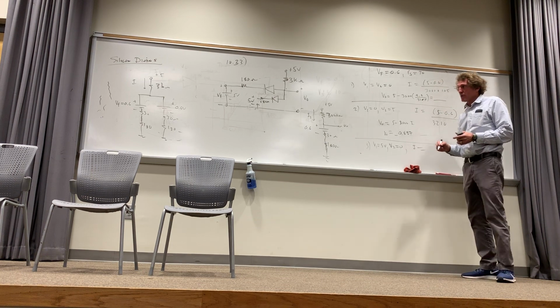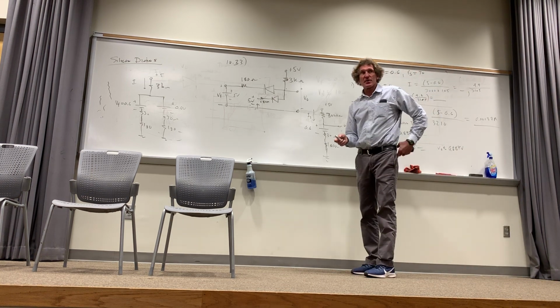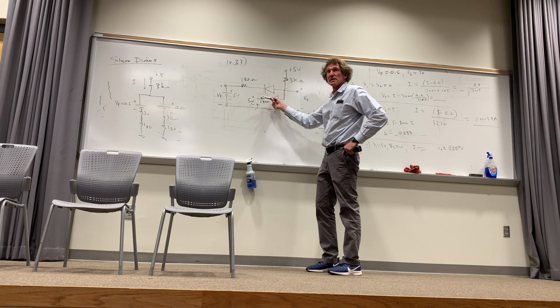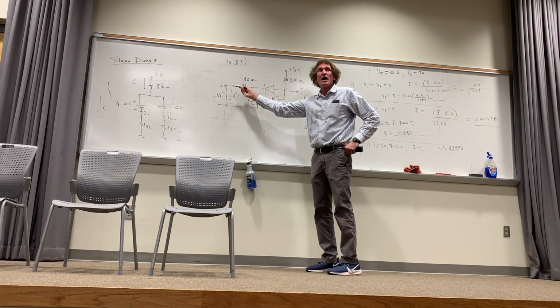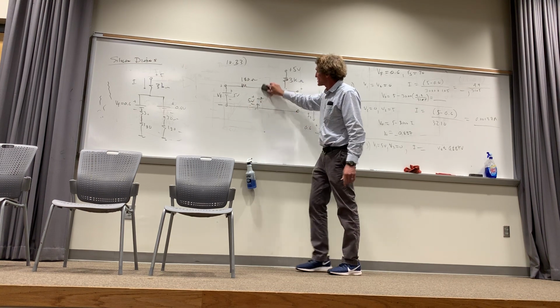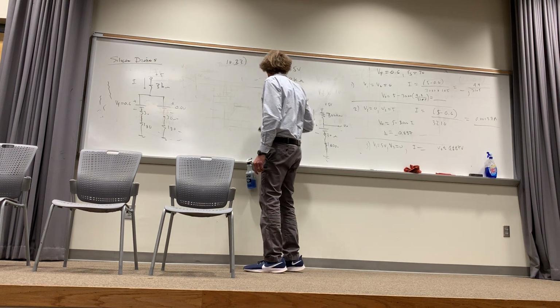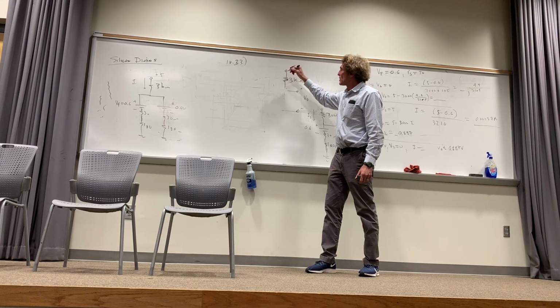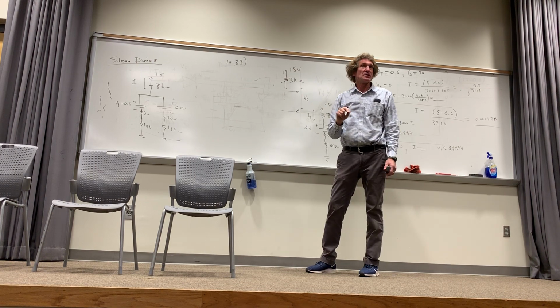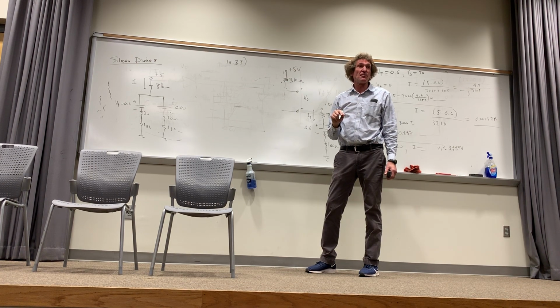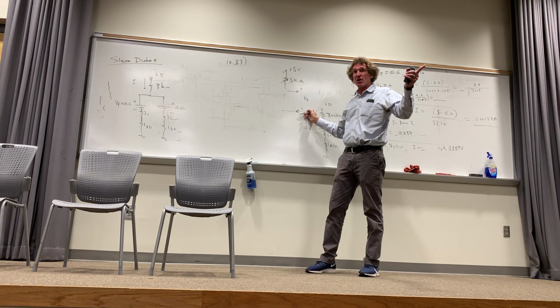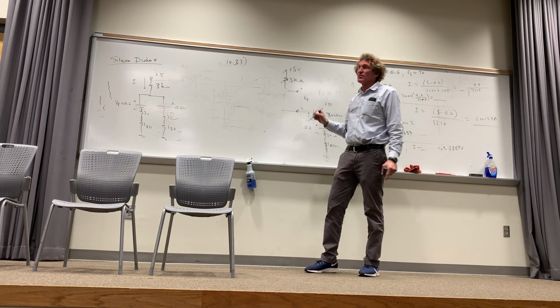All right. What about this one? Both 5 volts. Reason through it. How much current flows this way, class? No current flows, right? How much current flows here? What's the voltage drop here? 0, right? If no current flows, there's no voltage drop, right? How much voltage is from here to ground? 5 volts, all of it. There's no voltage drop. Agree, class? If there's no voltage drop, 5 volts is from here to ground.